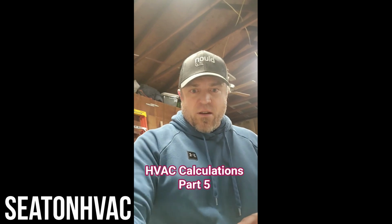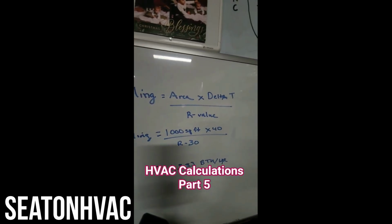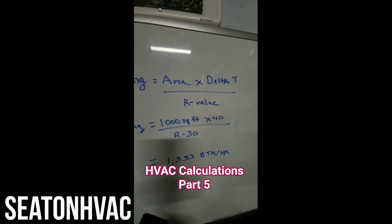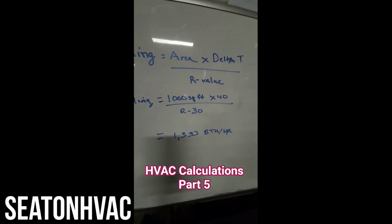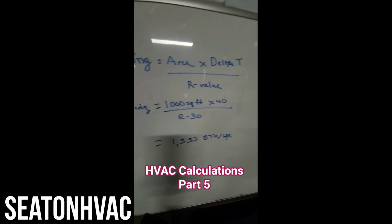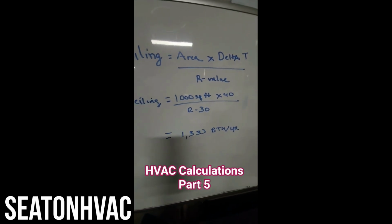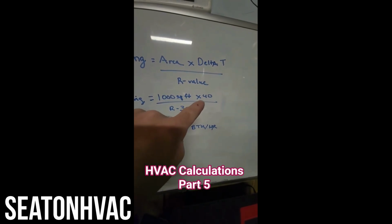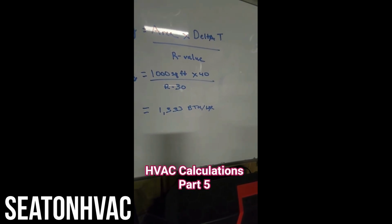Let me show you how that's converted here. Again, it's the same formula as the walls. Ceiling equals the area of your ceiling times your delta T, your temperature drop, divided by the R value. Say we've got 1,000 square feet of ceiling, with a 40-degree temperature drop between the inside and the attic, insulated to R30. 40,000 divided by 30 gives you 1,333 BTUs per hour.